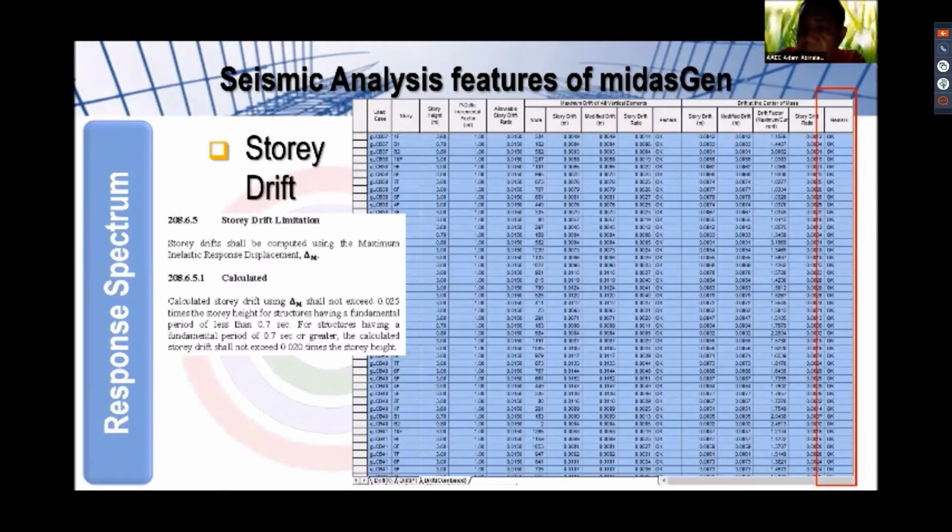So practically, even considering the design basis earthquake, the drift values are within the limit as prescribed in the code. Much more, even for the ground data that we use in the model, the results of the story drift check turn out to be within the limits.